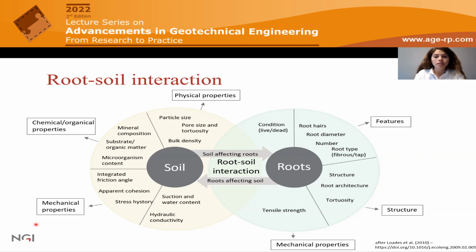Regarding mechanical properties, it's well recognized that roots increase the stress path in the soil, as well as the apparent cohesion, or in some cases also the integrated friction angle. And this all depends on the number of roots and the type of roots that are affecting the soil.